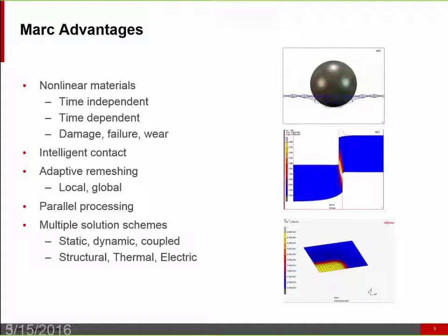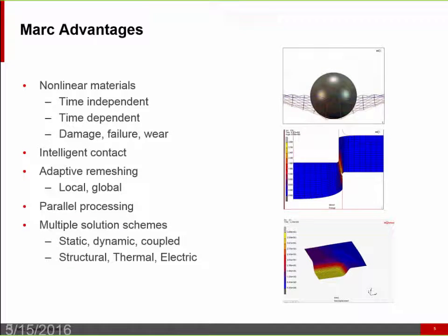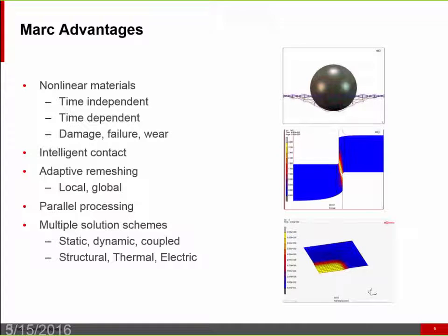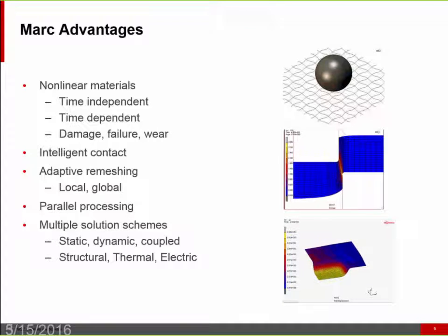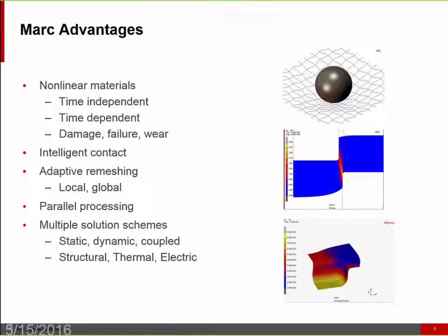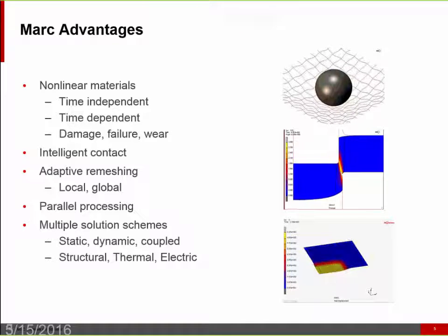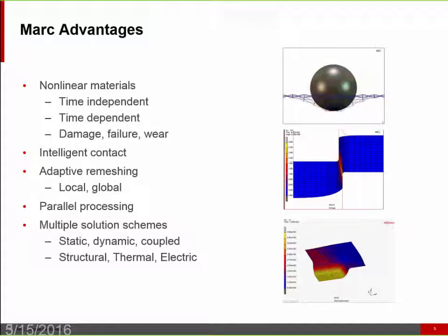In the first animation, we just need to create two contact bodies for this analysis. One is for all the beam elements, and the other for the rigid ball. And that's all for the contact setup. We don't need to create special contact elements and define contact stiffness. We don't need to tell Marc where are the areas contact might happen. Marc will model the contact between the beam elements and the ball, as well as self-contact among the beam elements automatically and correctly.